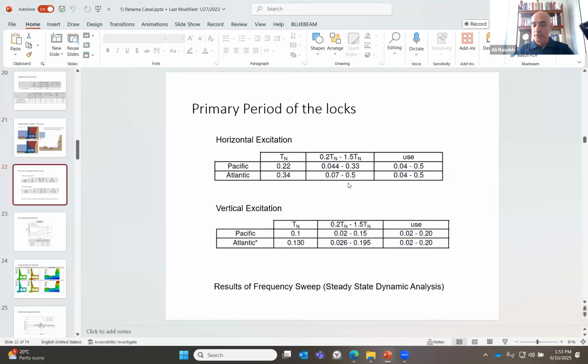Do you do any modal analysis? Yes, especially for dams, we start with a modal analysis. It's a good test to check the periods and also make sure the connectivities are there in the model. That's like our first test model to make sure everything is working.